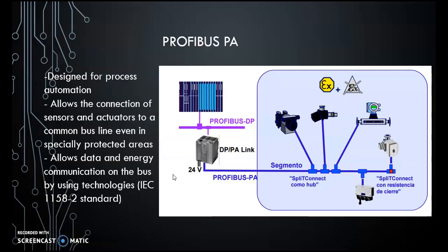The connection of Profibus PA transmitters, converters, and positioners is made with DP/PA couplers. Two-wire cable is used for the power supply and data communication of all equipment, resulting in easier installation and lower hardware costs, less startup time, trouble-free maintenance, low engineering software costs, and high reliability in operation.